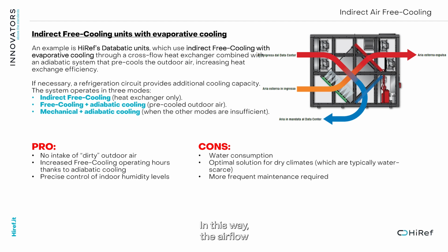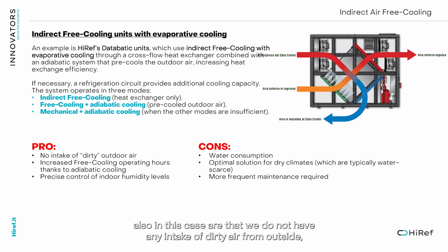In this way, the airflow that exchanges with the condenser is sprayed with atomized water, which reduces the condensation temperature at which the unit operates, thereby increasing the efficiency of the system itself. The pros, also in this case, are that we don't have any intake of dirty air from outside.